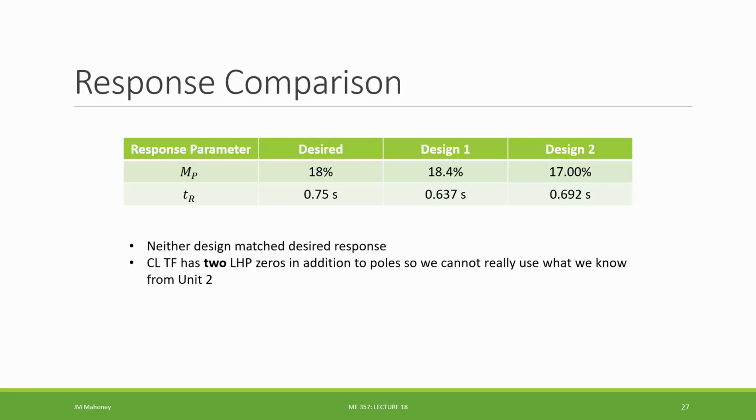All right, so again, going back to the closed loop transfer function, we were able to find it for both of the designs, but we had those 2 left half plane zeros. And they were complex conjugates of each other. They were both complex numbers. So in theory, we can't really get a good sense of how close our 2-zero 2-pole system is going to behave in relation to how the just 2-pole system would behave, that baseline. But the root locus method is designing it based on how the baseline second order system behaves. So we're not that close to it.